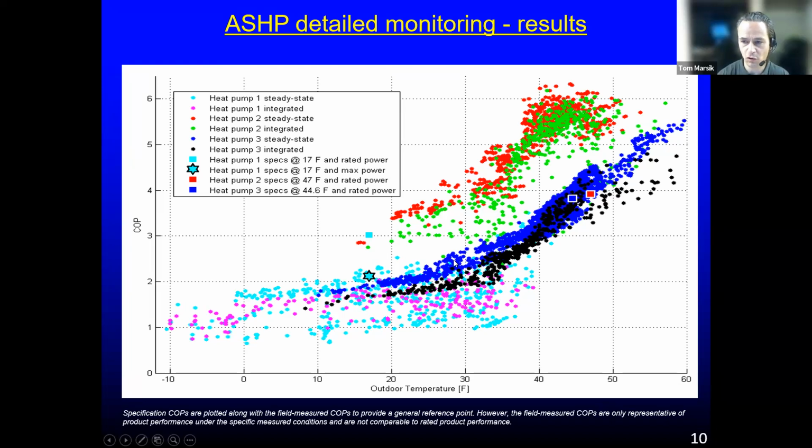Now, what happens in the colder temperatures, below, say, 40 degrees Fahrenheit or so? Remember, the coil on the outside unit is colder than the outside environment because it needs to extract the heat from the outside environment. So when we are looking at temperatures below 40 degrees Fahrenheit or so, the coil can be below freezing, and there's condensation on it, which below freezing turns into ice. And so the coil is icing up, and when it's iced up too much, the heat pump needs to defrost itself, which means it stops heating for a short period of time.